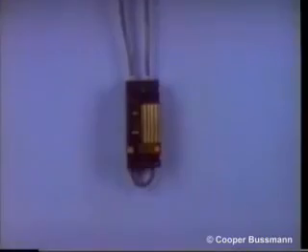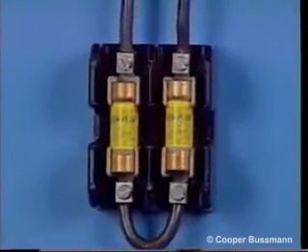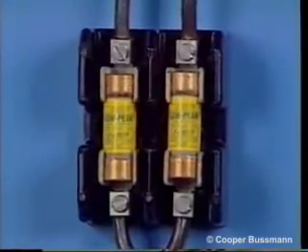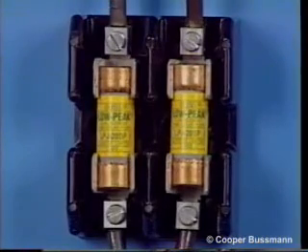In conclusion, circuit breakers and fuses must be applied so that they are capable of safely interrupting the short circuit current at their line terminals per NEC Section 110-9. Inadequate interrupting rating can cause both fuses and circuit breakers to violently explode and become a potential hazard. Modern current limiting branch circuit fuses applied within their interrupting rating will safely interrupt currents of up to 300,000 amperes RMS symmetrical.